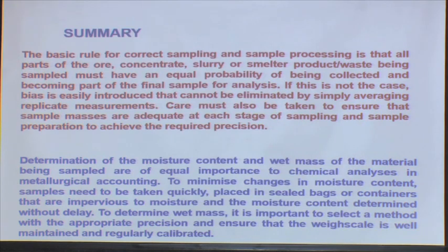I must know how many tonnes of material the conveyor belt conveys in an hour. Based on that, again go back to the Gy's formula. I must know that in one increment I must collect that much sample. It is not that at my wish or convenience I will take 1 kilogram. Okay. It is difficult, but you have to do it.